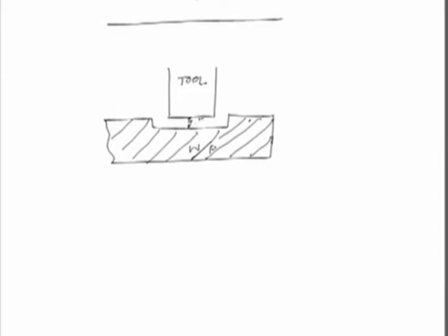Because of this sparking, not only will the work material get eroded from this portion and go as debris, but the spark at the same time will cause some erosion on the tool face as well.